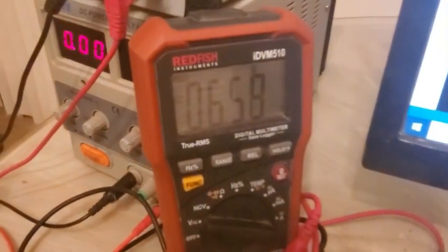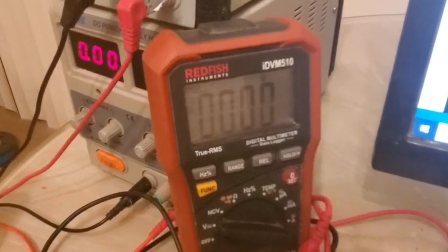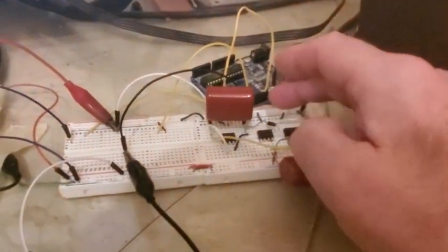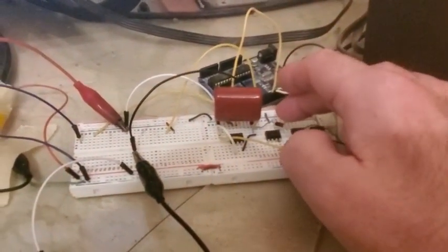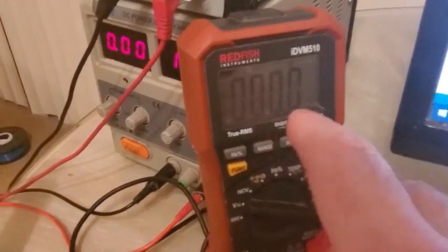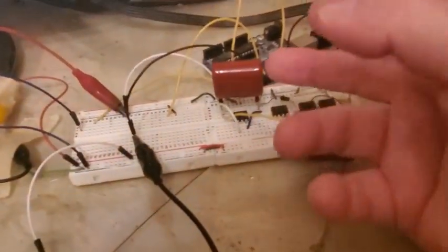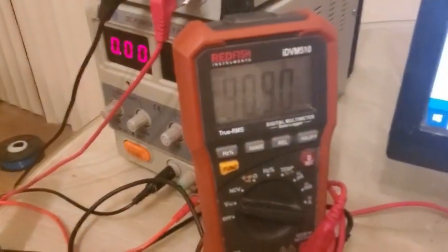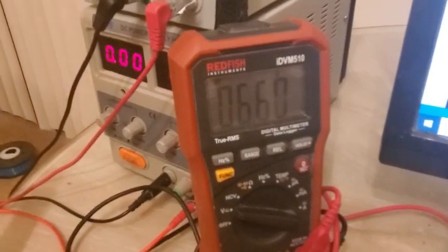I'm going to fiddle around now with the timing for this one and see if I can get it a little bit better. You know, if you get it 0.2 volts better than that, then you say, well, that's all from the voltage drop across the rectifying diode. And you wouldn't have that if you did synchronous rectification. So that's kind of neat. I'm going to fiddle around, but if not, maybe this particular diode has a 0.8 volt drop, or maybe there are other things going on as well. But that's not far off from what I would have expected.